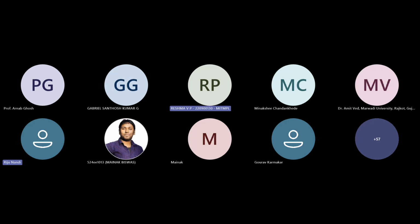Yes, for that emulator, partial shading is not available. For this PV emulator, this value will be changed. The PV emulator and the PV panel are different. The PV emulator is only possible for uniform shading; for non-uniform irradiances, it is not possible. I have shown how to track the maximum power point at a particular value of irradiance.